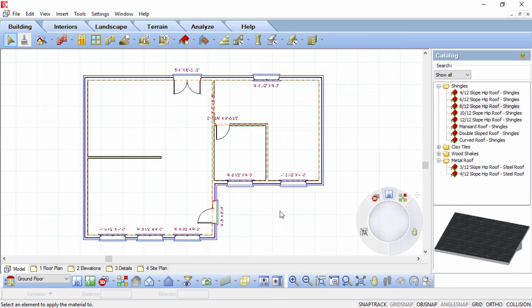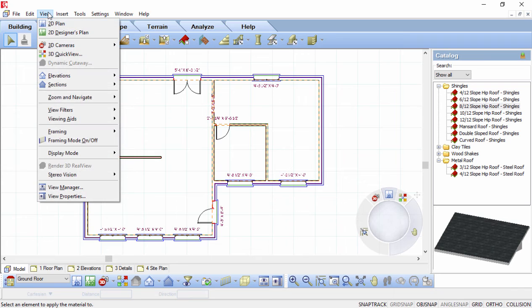Using the Kitchen Builder wizard, you can quickly and easily create a kitchen layout that includes upper and lower cabinets, a sink, refrigerator, and stove. There are a number of layouts and styles to choose from. Once the kitchen has been created, you can move, edit, and delete items, as well as add more elements if you want. Let's create a kitchen now.